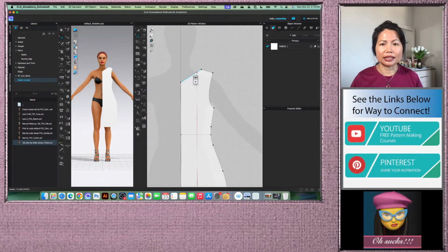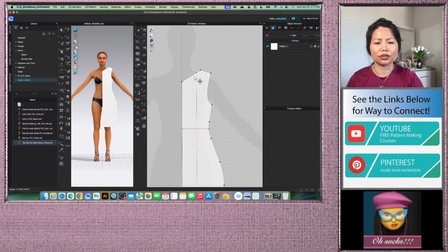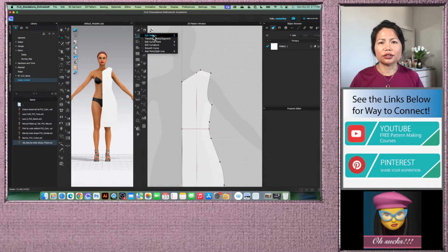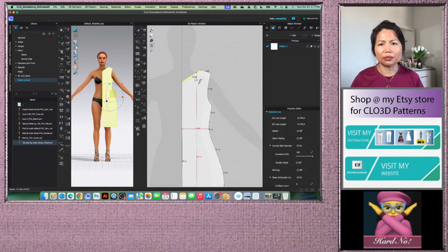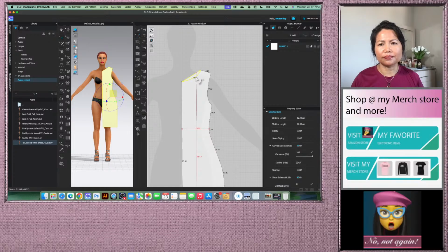And by the way, the neck itself is a crew neck. We want to turn that into a curve as well, so use the curvature tool. With the curvature tool, we can simply click or press the letter C here, a shortcut key, and I'm going to click and then bring it down right there a little.